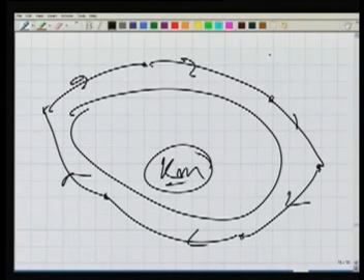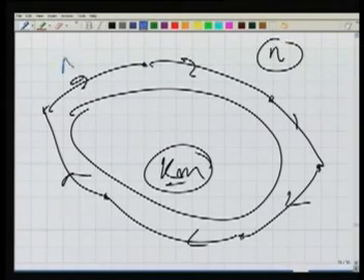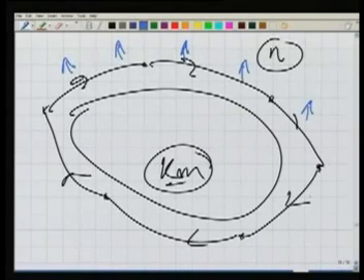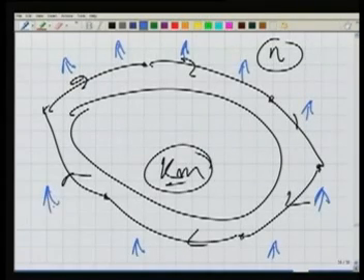And N stands for, when we are doing this exercise, I might have kept my instrument in several places. How many settings of the instrument? All these are N. So we can use either the kilometer or the N, and we have to use the same throughout our entire project. So N is the number of settings of the level instrument, because we know,